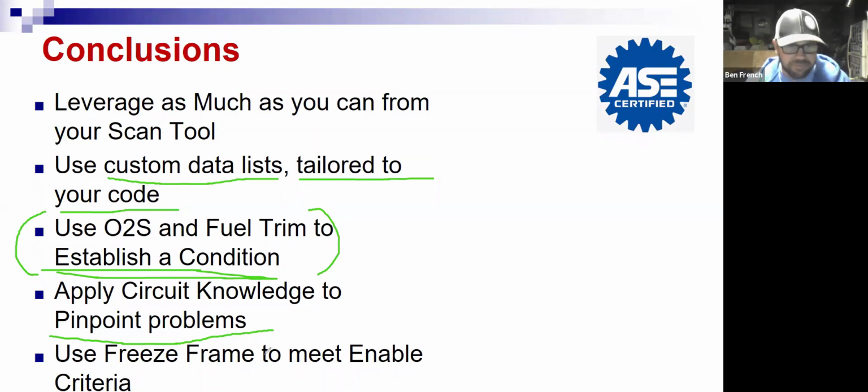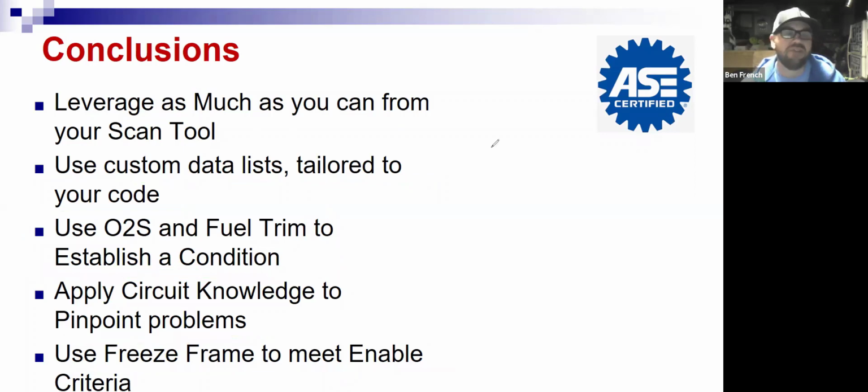So always use freeze frame data to meet your enable criteria to verify your repairs, right? Those are some of the things that I was hoping you would take away from tonight. I showed you different ways to look at your scan data, and we ran through some different diagnostic scenarios.